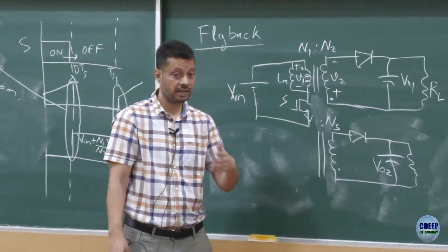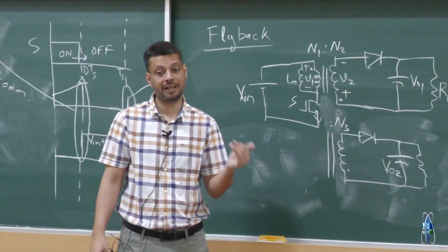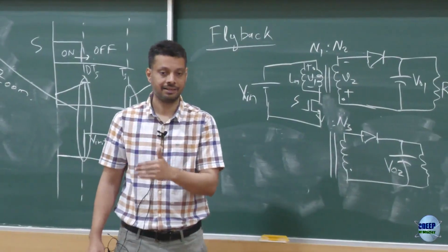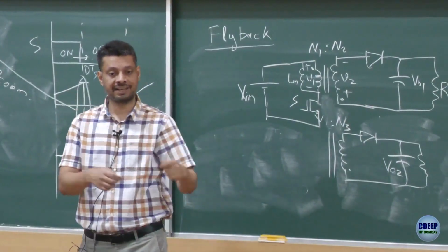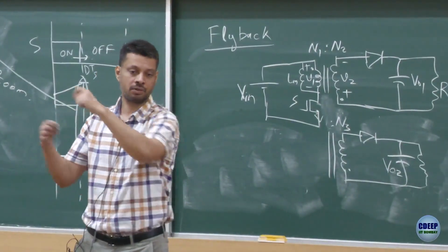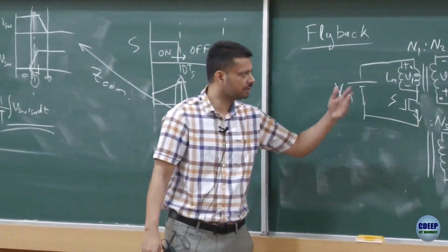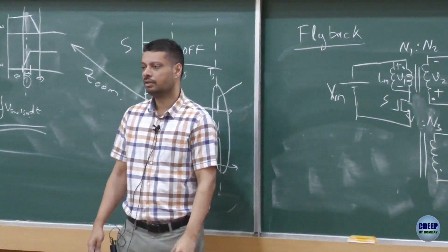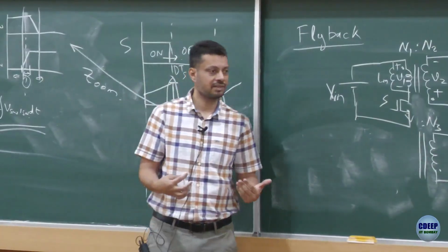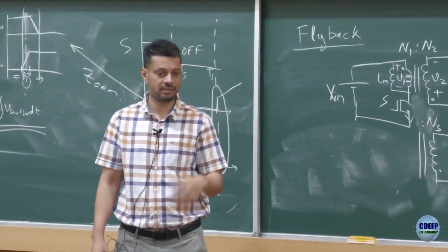No, use it for gain. In fact, I told you, the first application for flyback was actually providing a very large gain. To create a very high output from the battery supply, from a 12 volt supply, you create a very large output, right? So you use it for high gain as well. Some of the consumer applications you may not see, but they are there anyway.